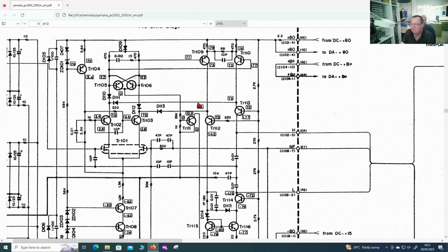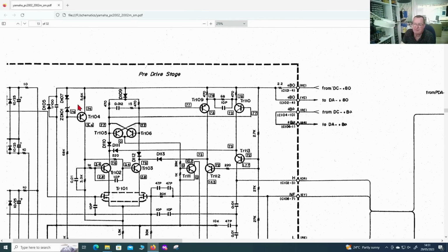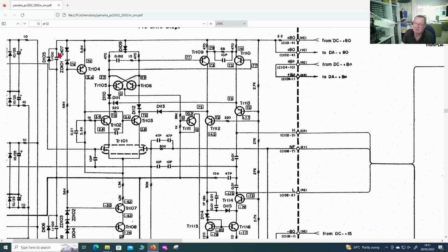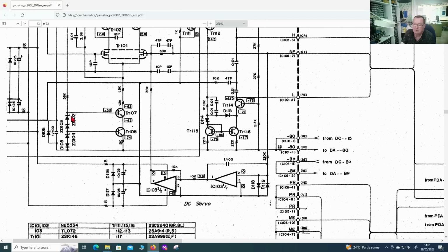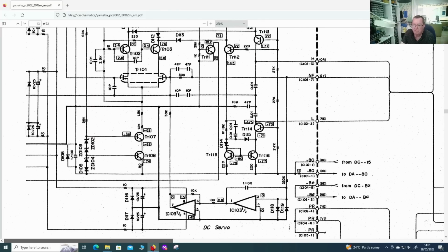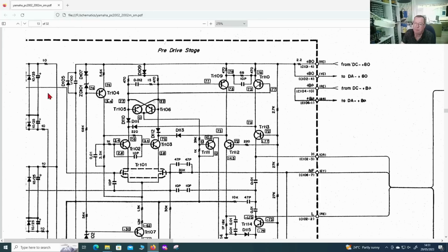So at the moment, I'm not exactly certain where the problem is. I don't see anything obvious. We could have a faulty capacitor. I mean, there's a capacitor there that goes to ground. This heavy track is ground, so maybe a faulty capacitor would do it. In fact, I'm sure that would do it. The front part of this appears to be missing, but this voltage rail only goes as far as here. So yeah, maybe a bad capacitor there.